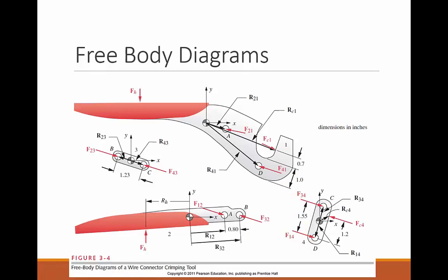Okay? So we have 8 of those constraints, assuming that I looked through carefully. F4,3 is equal to minus F3,4. That's one of those equations. So we only need 17 equations. We have 12 plus 8, a total of 20 equations. So we need 17 equations. We have 20, and we have 3. That means we have 3 redundant equations. Okay, so we'll have to get rid of those three redundant equations, and now we're set up.